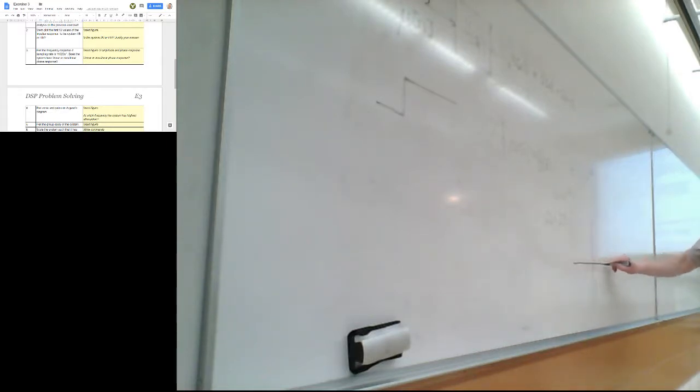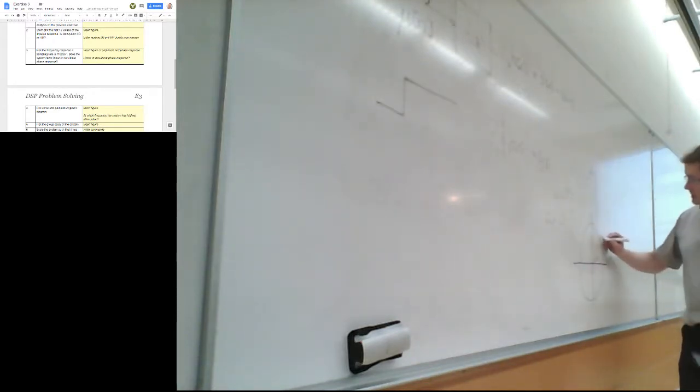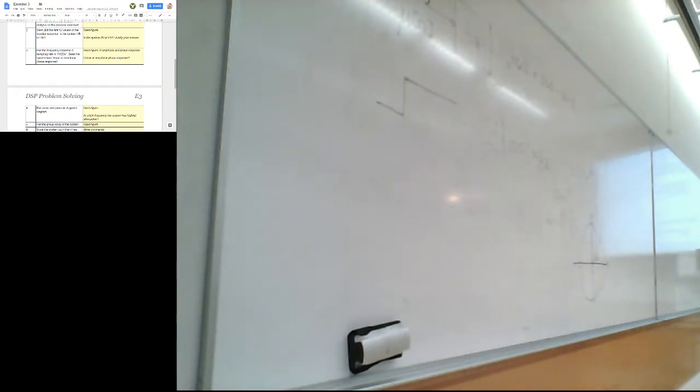Oh, much better. So on the unit circle in complex plane, angle omega is right there, and that point here, e to j omega, is basically here, like that. Good. So basically, the frequency response is the same as you evaluate the transfer function on the unit circle.